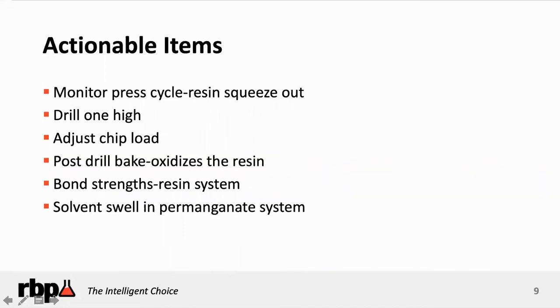Obviously, the press cycle, the lamination cycle itself, heat up time, the pressure that you use to move the resin through the package, the stack up, anything you can do to minimize resin squeeze out and optimize the press cycle. Again, proper heat rise, proper use of the heat lagging materials. That minimizes resin squeeze out. That prevents what we call fat glass, where the glass is actually pressed more on the copper instead of the resin, because that typically ends up causing that wedge to open during drilling.